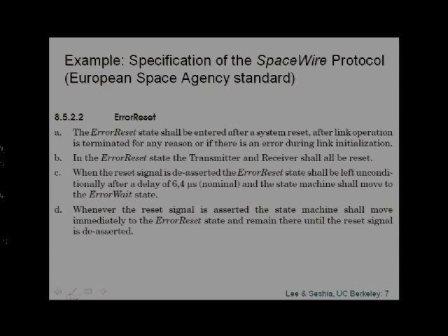This could actually have implications for cyber-physical systems, for embedded systems, because of the amount of time that elapses. There's some physical process going on, and if your SpaceWire system has to be reset in time before something bad happens, it had better be done quickly, right? So there's an ambiguity in this specification already in English. Should it be entered immediately after, let's say, a single cycle? If this is a synchronous system and you have a clock, is it after 1 clock tick? Is it after 2 clock ticks? This English specification doesn't say that.